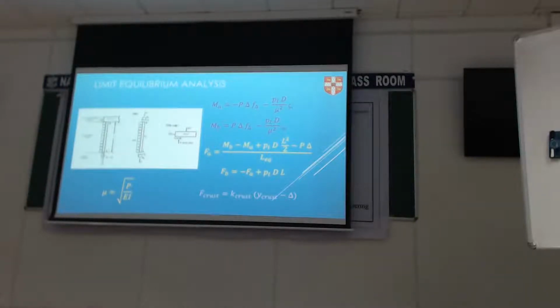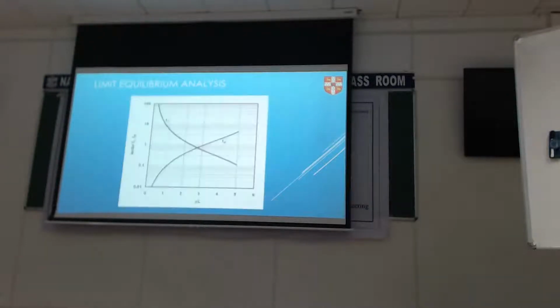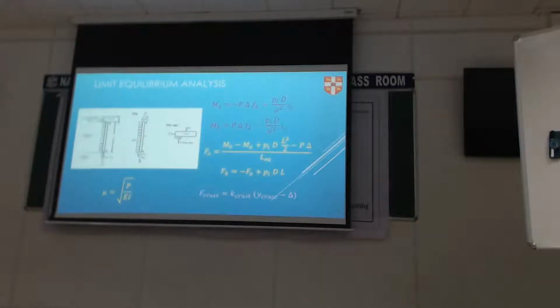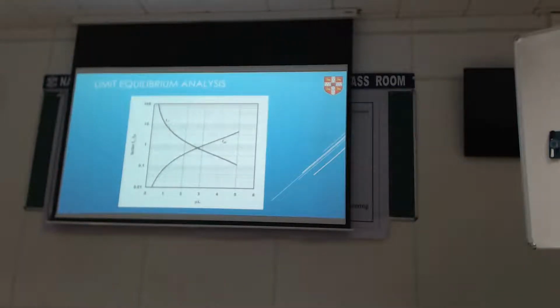So this gives me a way of doing my centrifuge test or borrowing data from other centrifuge tests and saying, right, I'm going to make these curves to take that experimental evidence into account. So you don't need to do experiments every time you need to design a pile group, which is foolish. Okay, so that's where those two factors are coming from. We've drawn these based on the experimental results we got, so that you don't have to.